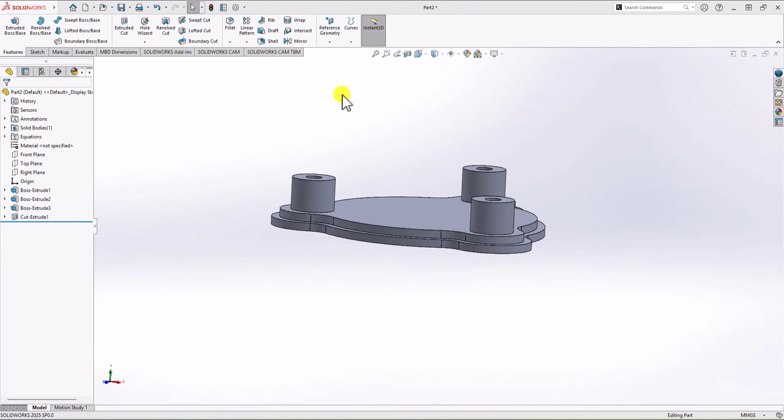Okay, awesome. So now we have the geometry. It's time to check the total volume or mass and make sure that we have the correct geometry. So this question is a little bit different. If we go back to the question and check it, we see that they actually defined a material in this question, and we need to check the total mass, not total volume. So let's take a look at this question again.